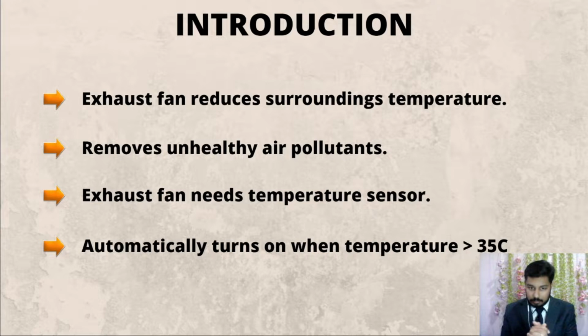a spike in temperature. So therefore, in this project, exhaust fan will be automatically turned on when there is an increase of temperature, specifically when it goes above 35 degrees Celsius, because 35 degrees Celsius is known to be a very warm surroundings. So that's why 35 degrees Celsius has been set where the exhaust fan starts to turn on.